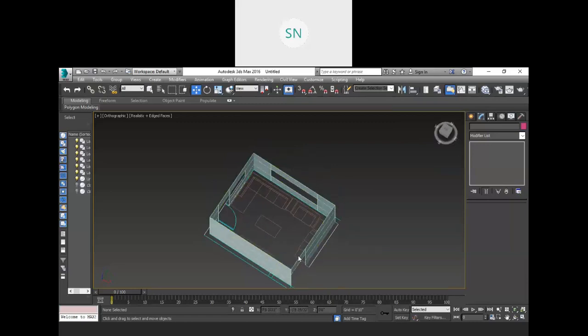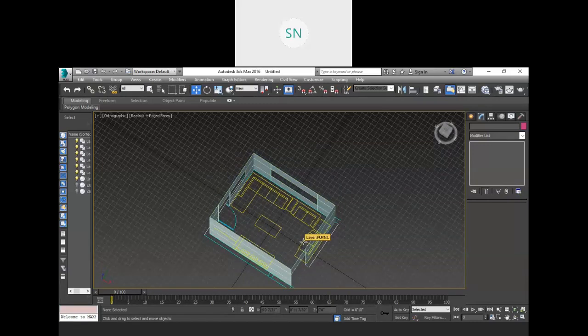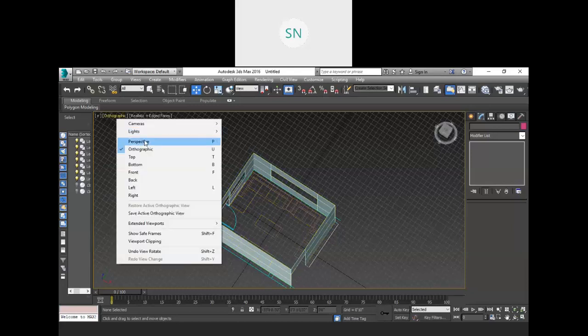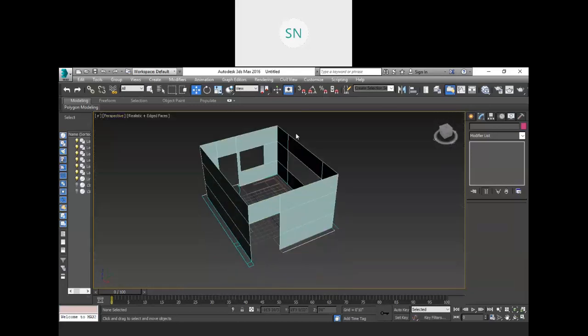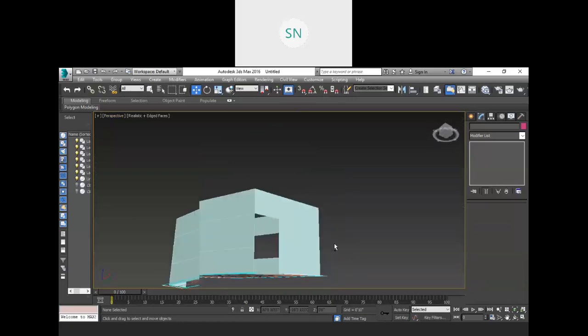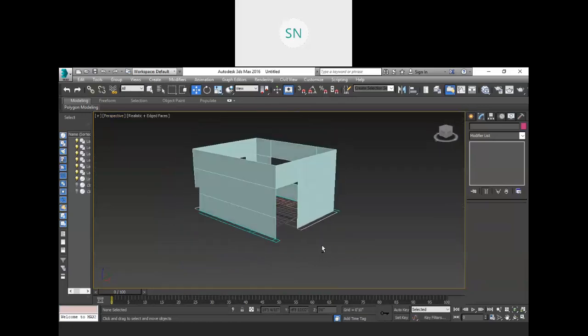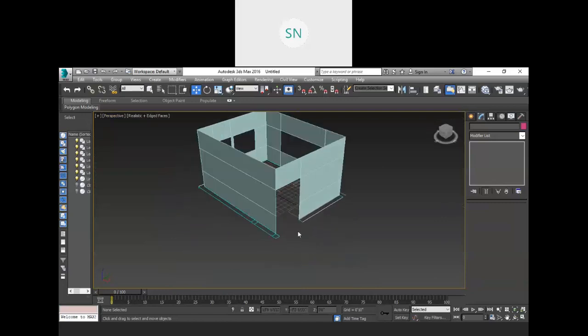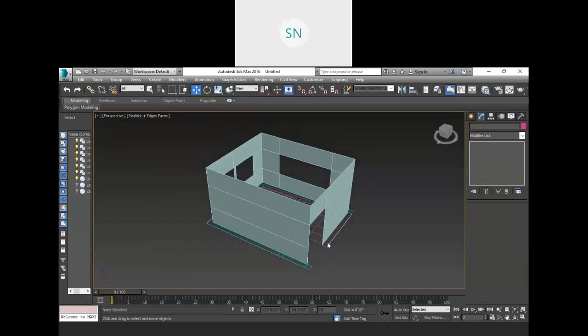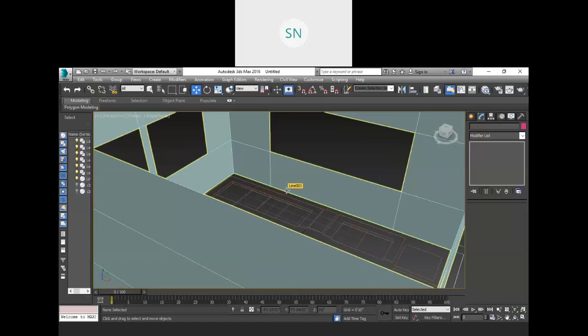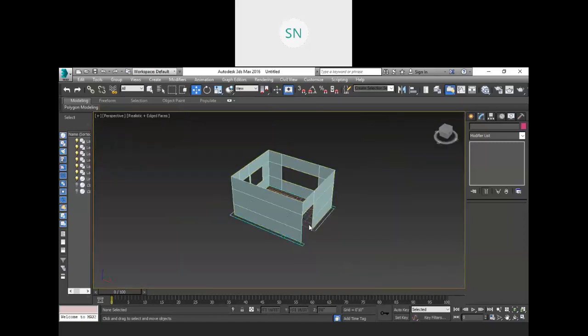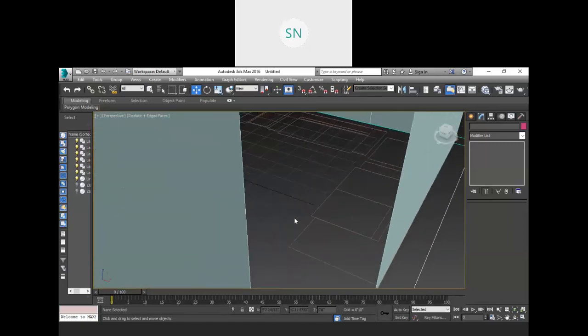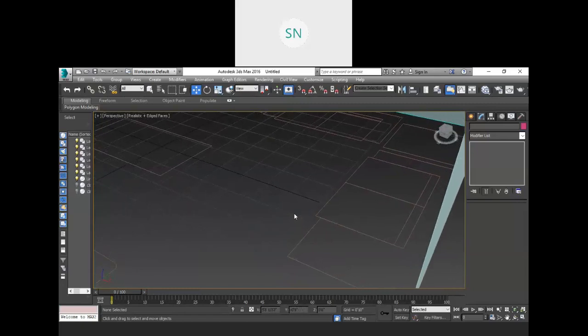See, if I turn on this grid, this is our origin. Go to the perspective, you will get my point, right? If you are in perspective mode, then it will give you some kind of problem while orbiting and in the zoom in and zoom out. Sometimes you roll your scroll button further and further, but it is not going to zoom in.